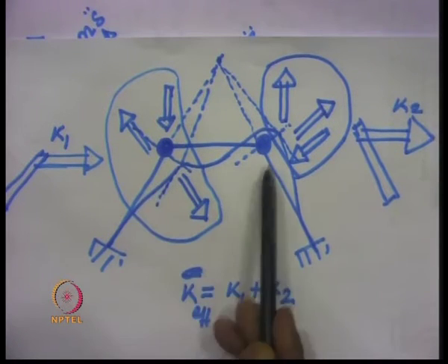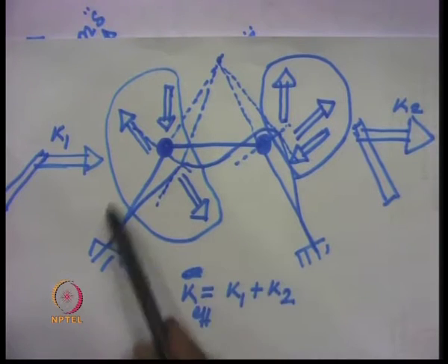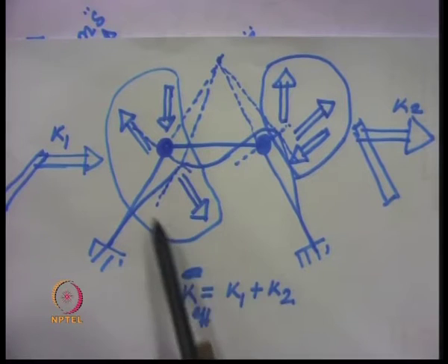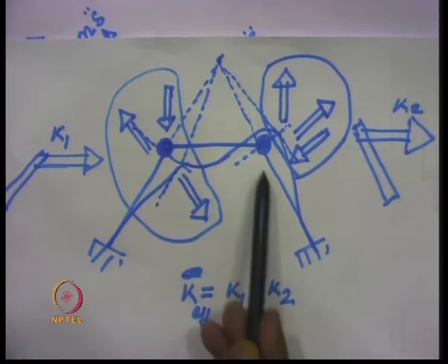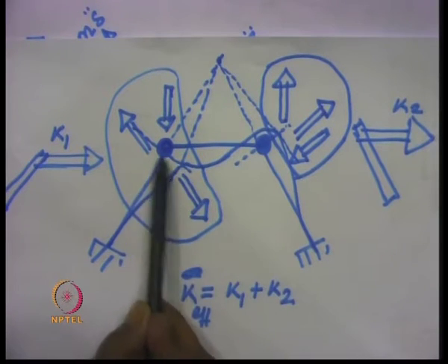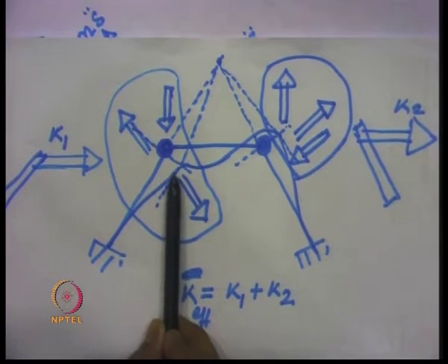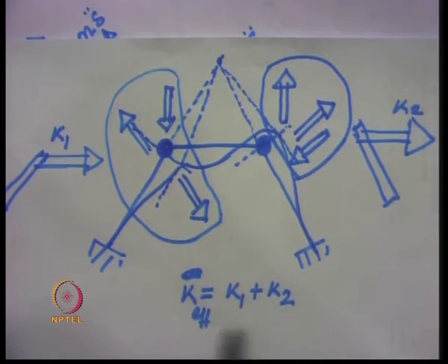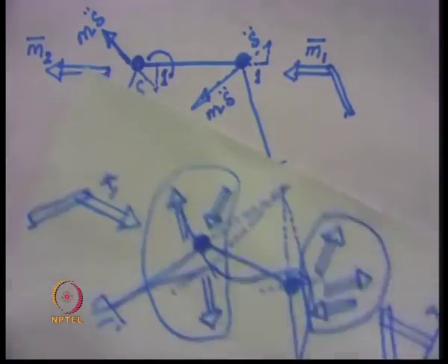And these forces which are coming onto the leg simply pass to the support, and there is no shortening of the member in this direction because it is assumed that the members are inextensible. So, in this particular fashion one can find out the value of the stiffness for the inclined leg portal frame.